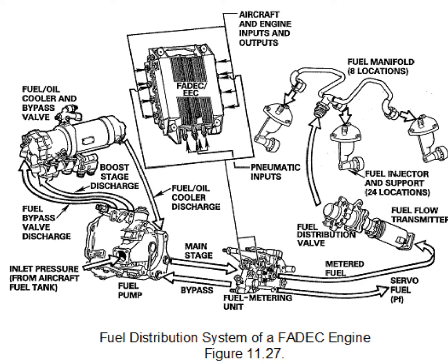What engine variables are sensed by a hydro-mechanical fuel control? RPM, compressor inlet pressure, temperature, burner pressure, compressor discharge pressure, EGT, TIT. What type of fuel control unit is used in turbine engines? Hydro-mechanical, electric fuel.